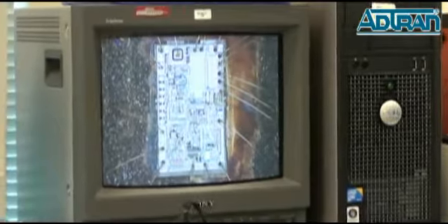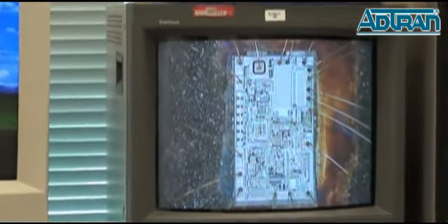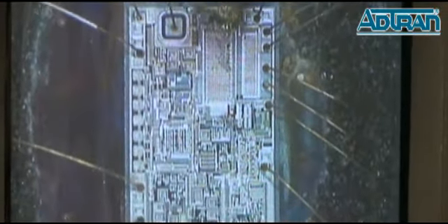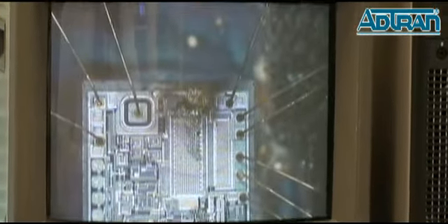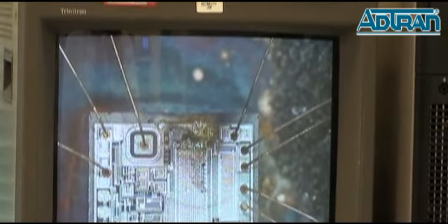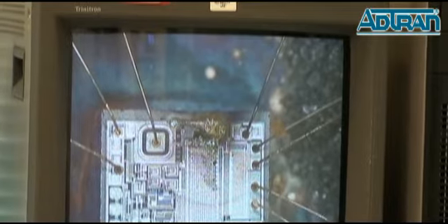This is actually a normal integrated circuit. Okay, as you see, it's clean, there's no damage. But when you go over here to this sample, you see severe electrical overstress at the top of the die surface. And this is an indication of most likely extremely high voltage.